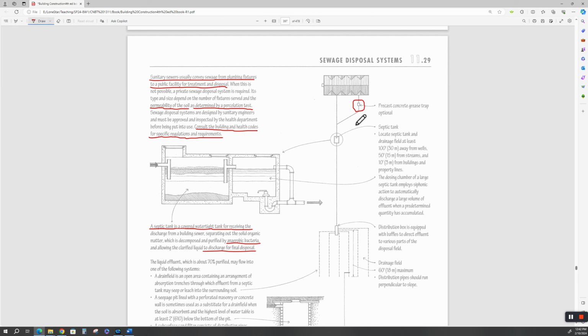Now let's talk about the darker side of these. Eventually that grease trap's going to get filled up. You got to bring a septic company out here to pump the grease trap out, or it'll start backing up into your house. So this is typically, if you're allowed to have a septic tank, your grease trap's first, it flows over here, it goes into the septic tank, and eventually these solids build up, and your septic system will not allow you to have as much flow through here. So you got to have them come out and pump the solids out.